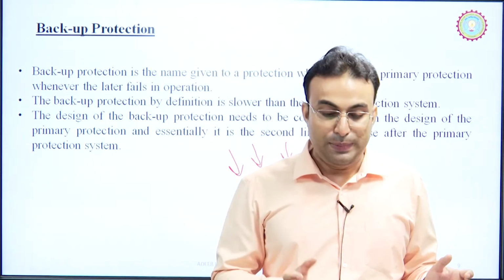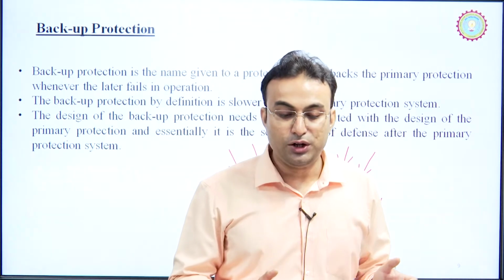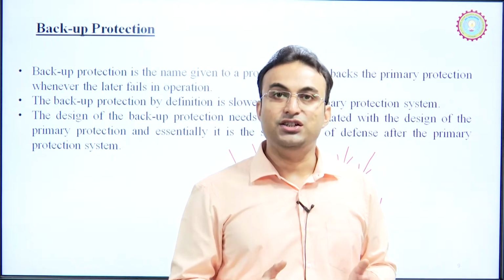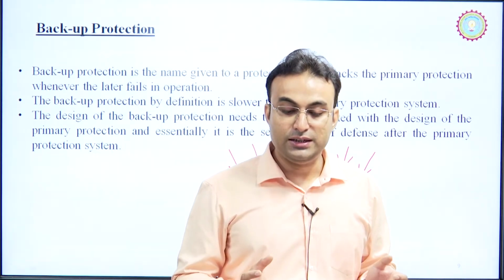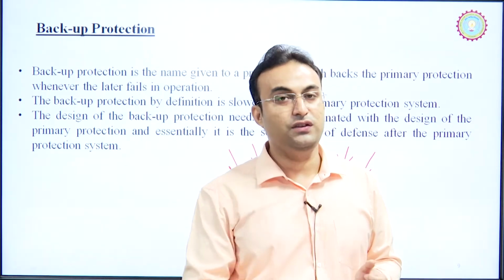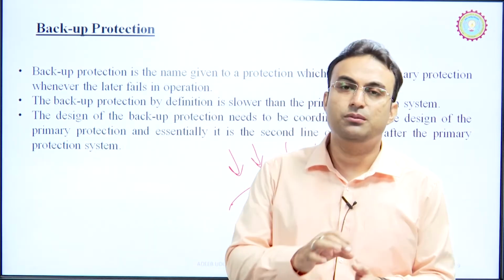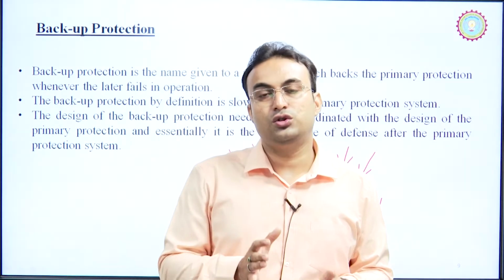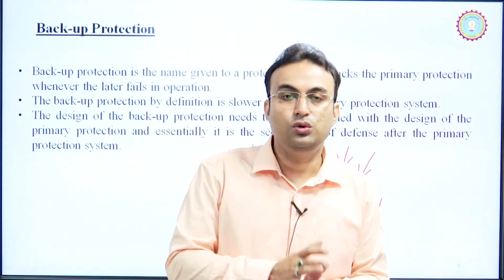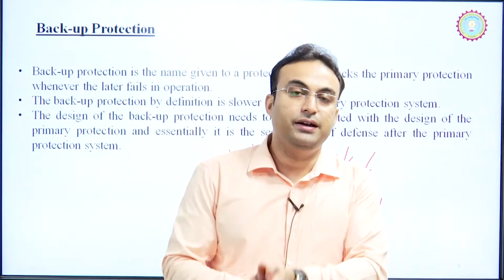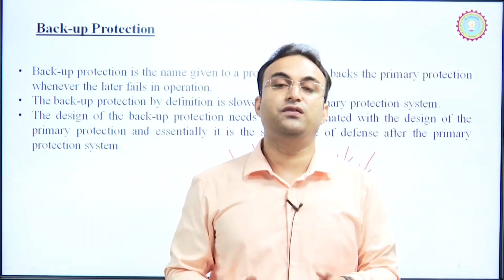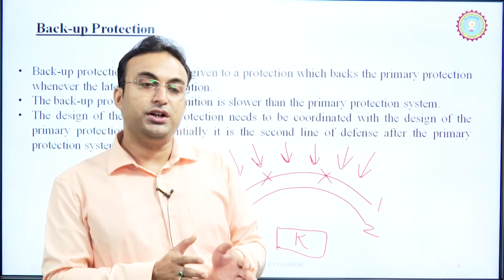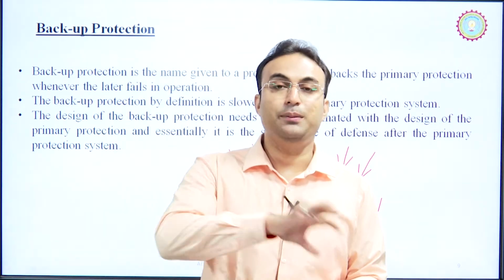The design of backup protection needs to be coordinated with the design of the primary protection, and essentially it is the second line of defense after the primary protection fails. So, that is very important. We have some timer settings, so that if one protection fails, we include some secondary options, some backup protection, for the protection of this zone. So, we have some graded protection, or we can say some line-up protection.